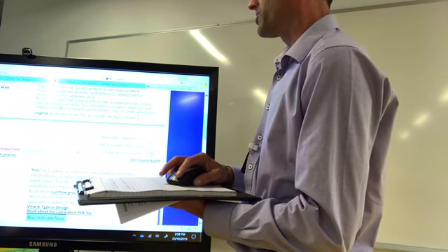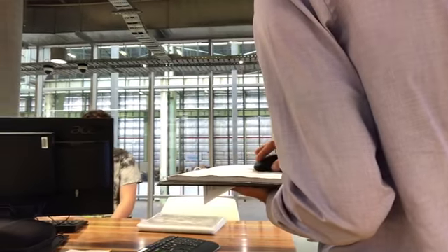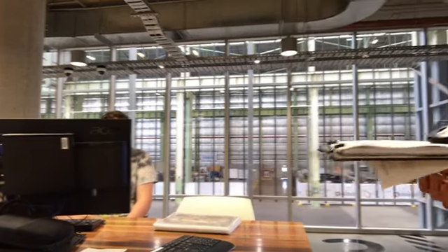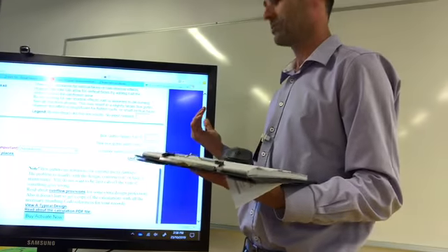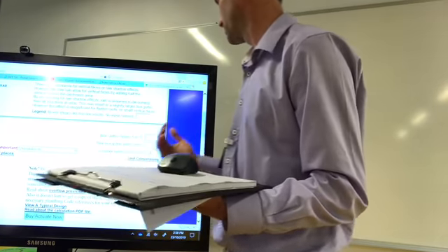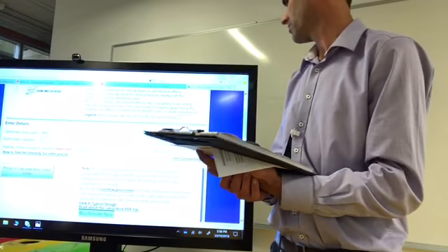So then you punch your numbers into there. Let's go catchment. Our roof there is around 400 square metres, roof slope of 5, and box gutter. If we have a look at our box gutter information, our minimum fall for that box gutter is 1 in 200. So we'll go with that minimum. And for our trial box gutter width, I suggest putting in 300.